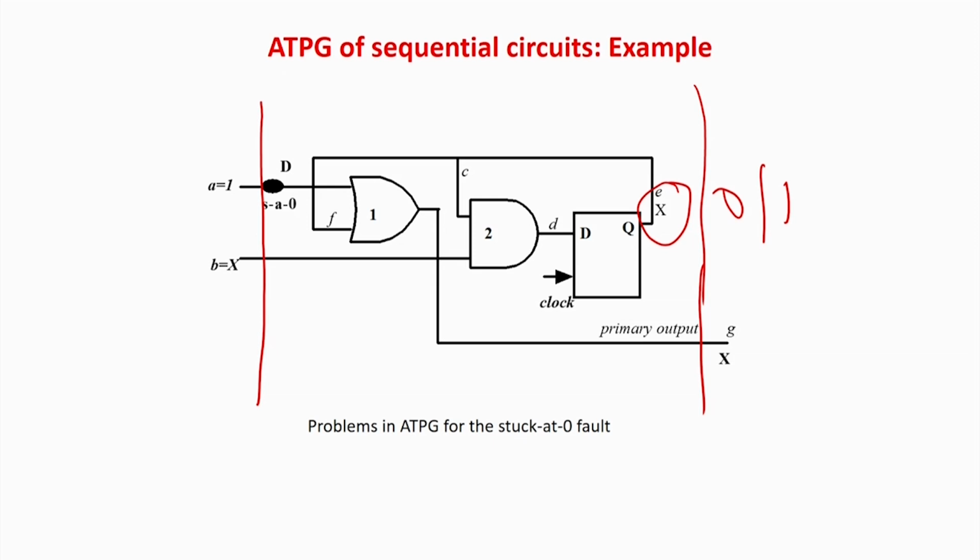So now that fundamental is settled, we do not know whether it is a 0 or a 1. So I have put an X, and then this one will also be X, I do not know what the value is, this one is also going to be X. Now we know that it is a stuck at 0 fault. So what we have to do is put a 1, that is the sensitization step. So what is the value here? The value here is D, that is normal case 1, failure case 0, that is very obvious.